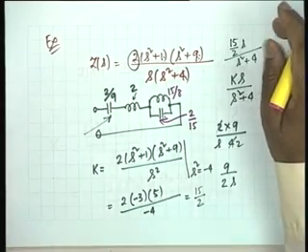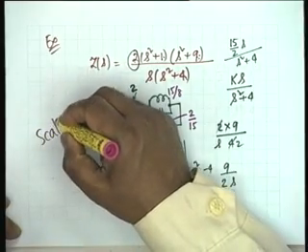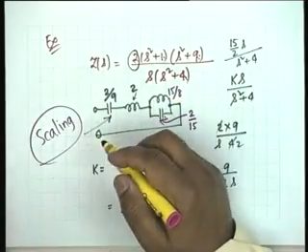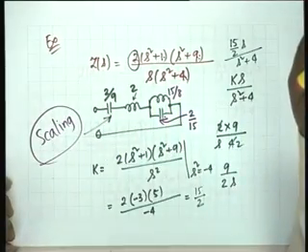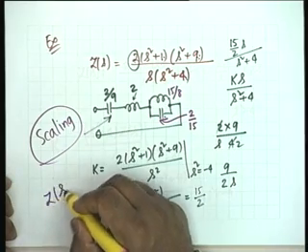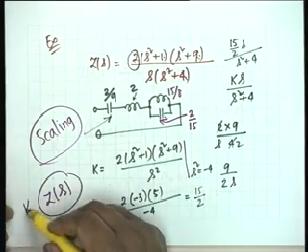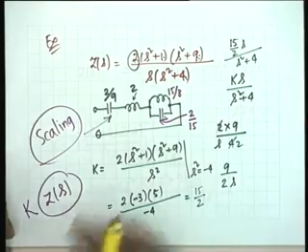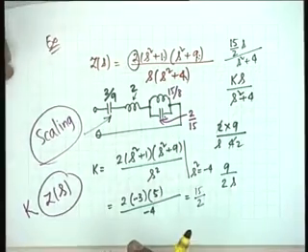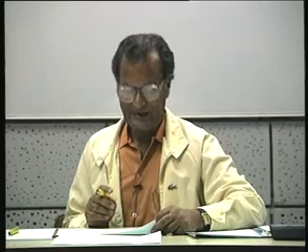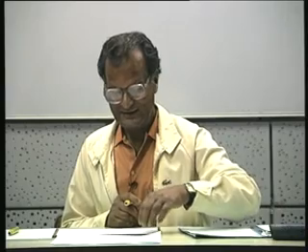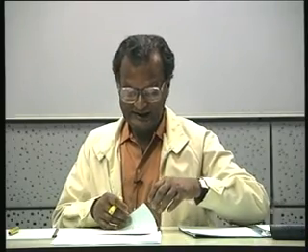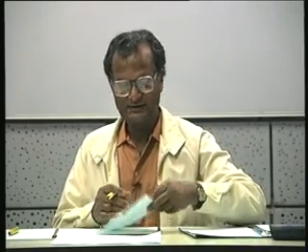This is called scaling. S-C-A-L-I-N-G. That is the principle, extremely simple principle. It is that if you know the synthesis of Z of s, then you also know the synthesis of Kz of s. All that you have to do is to change the inductors, multiply them by k and divide the capacitors by k. Now instead of an LC network, if I had RLC network, then what would have happened to the resistors? So multiply the resistors by k.